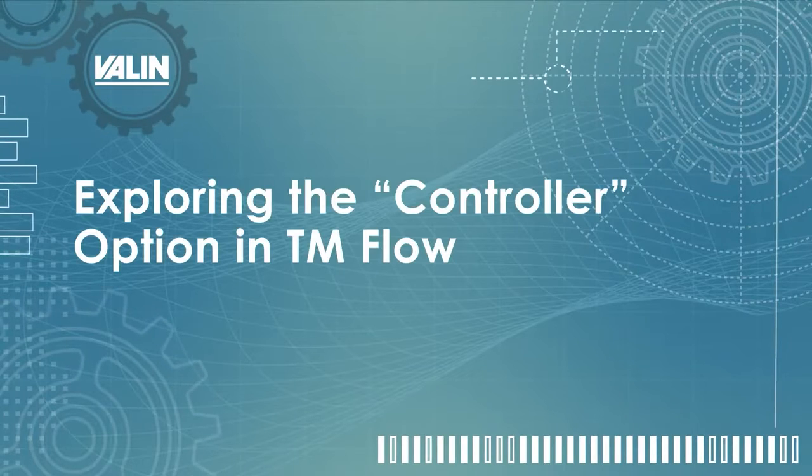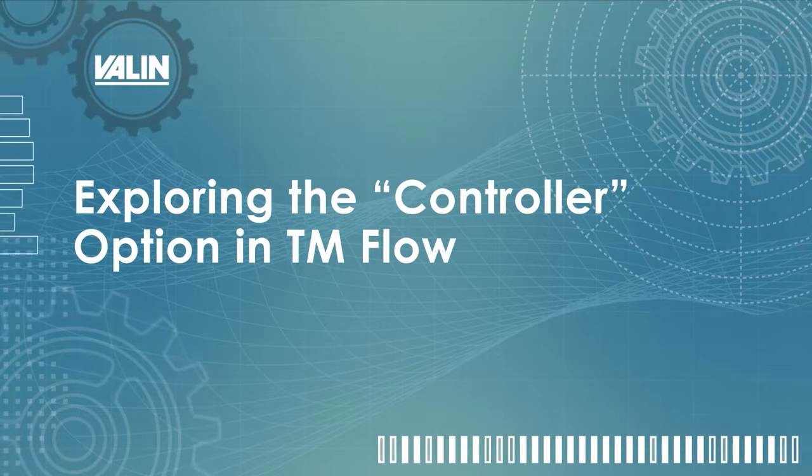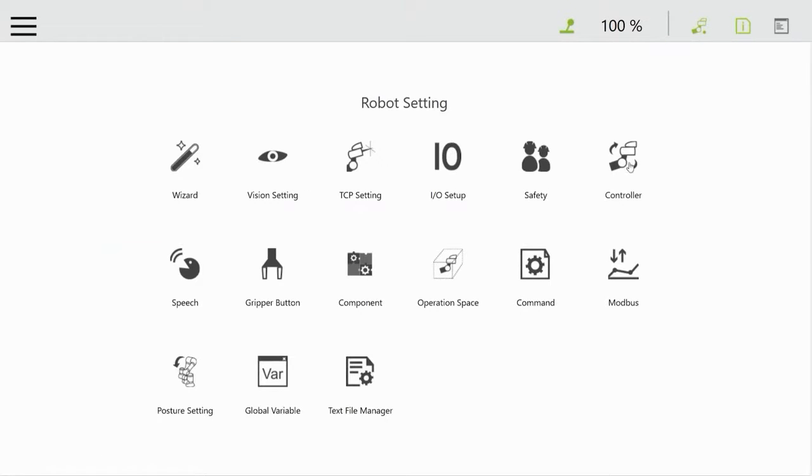Next, we're going to explore the controller option. The controller option is available in TMFlow in several different places. We'll look at all of them. And the controller option is how you manipulate the robot and check I/O and stuff. Once you're logged in, you'll go to the setting menu and then controller. This is the first way you get there.